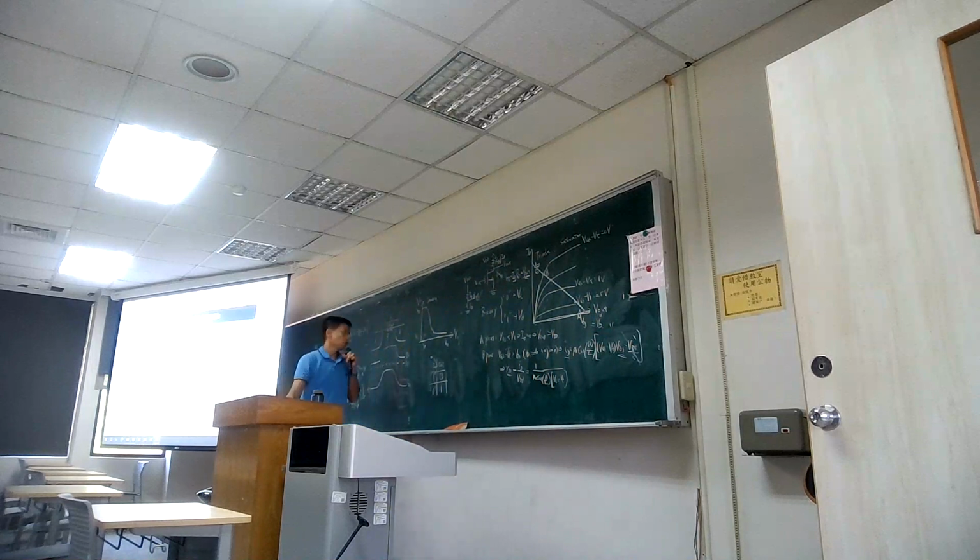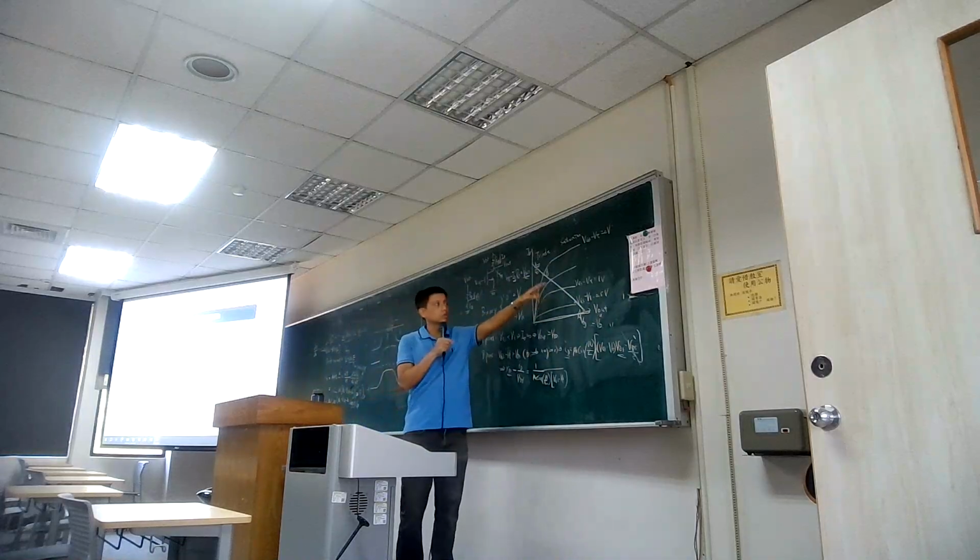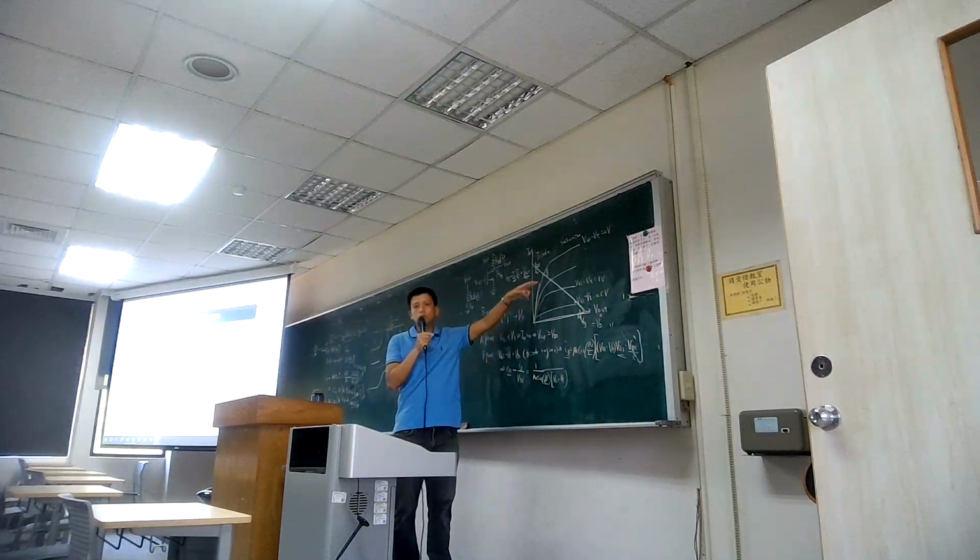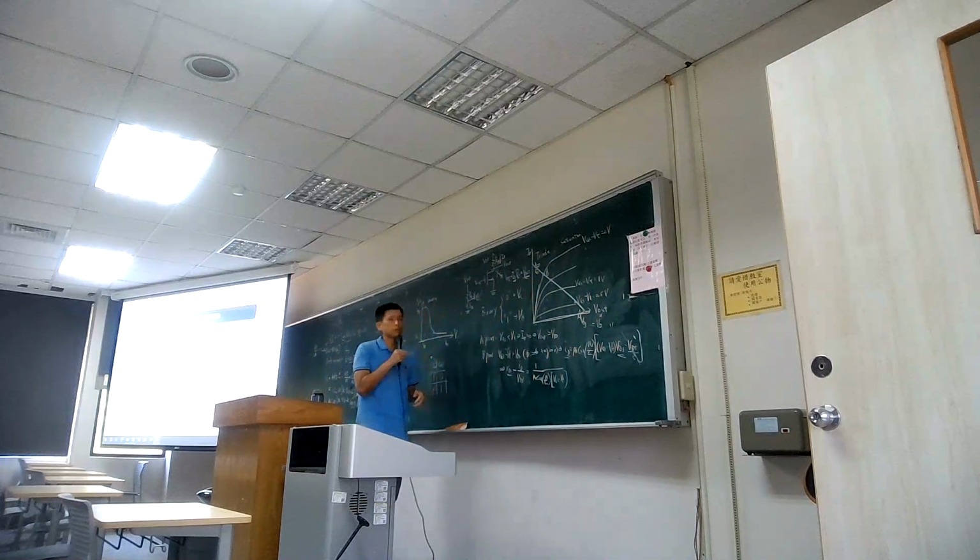And here is the part we call the high and low voltage. And the low voltage here. So you can think that by balancing the different input and output, once your input voltage is really low, that doesn't turn on the circuit, you get the output as 1, which is VDD. But when you have the input voltage as 1, a high voltage as the input voltage, that means you drive your circuit into the triode region.